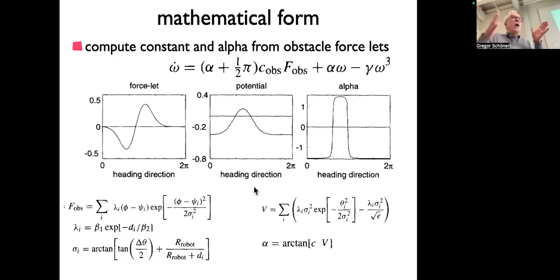And we use that as an indicator of whether there is an obstacle there. We make it a little sharper with this alpha. That's an arctan, but you could use others like a sigmoid, so that we take the range where this is positive and make that positive. And then we also use the negative part of that to know that's where there's no obstacle. The threshold for this is like the half width of that.